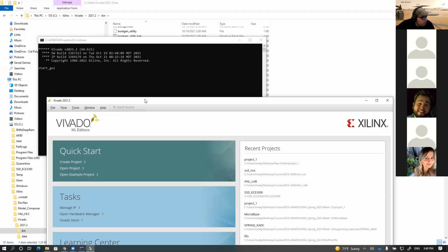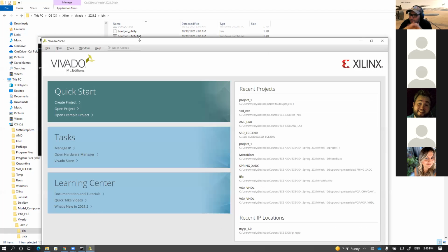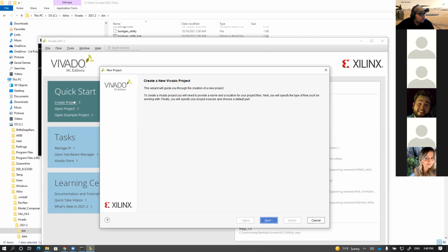Okay, now we open what? Vivado. Sounds good? To start a project with Vivado, what are you gonna do? You go into Create Project. Can you see what happened now? I got a new window that says Create a New Vivado Project. Can you see it? Yeah, we can see it.